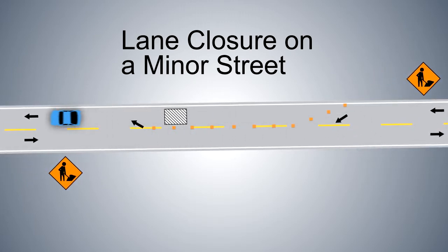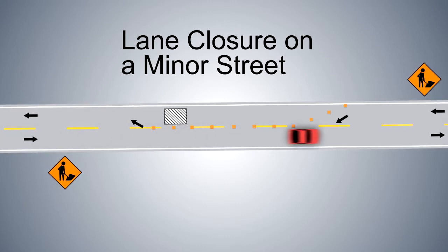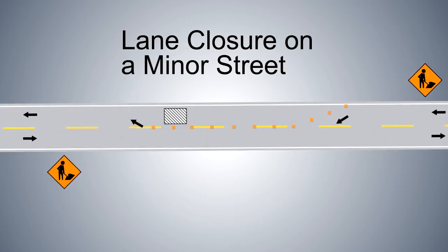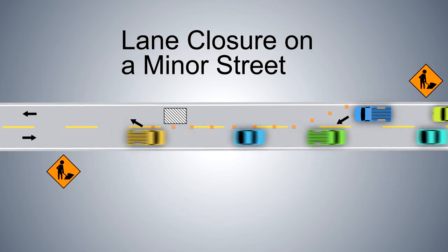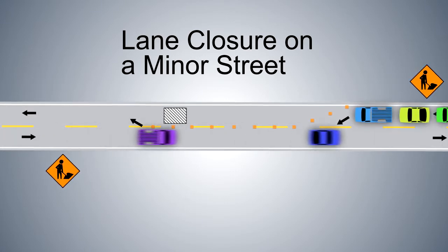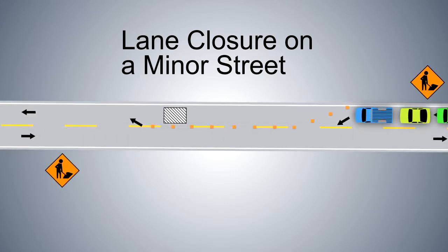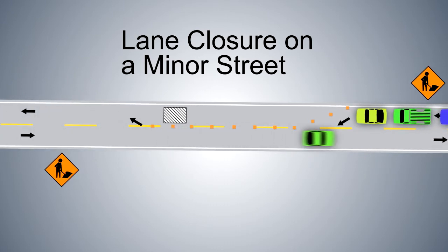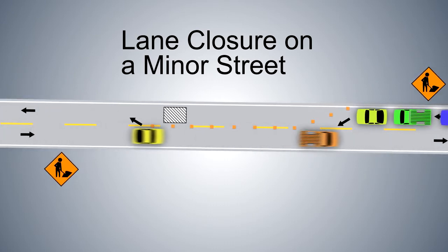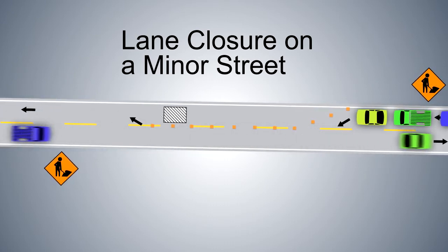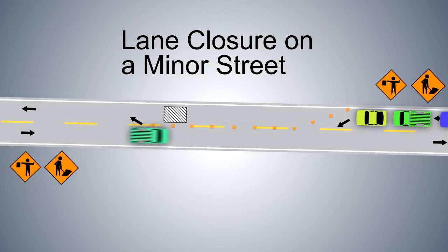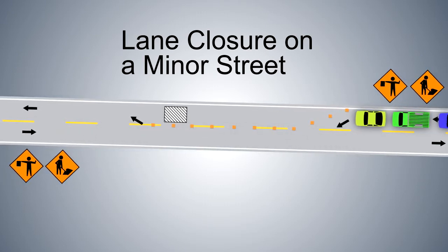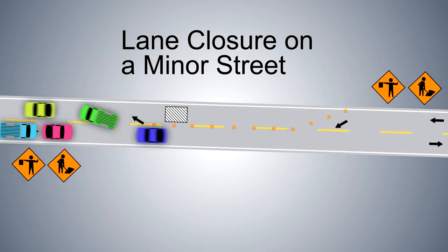However, when he arrives at the work zone, the supervisor sees heavy traffic in the eastbound lane and a backup in the westbound lane. To pass the work zone, many drivers accelerate too quickly. In situations like this, when traffic does not self-regulate, the standard in the MUTCD requires the addition of flaggers, which the supervisor immediately arranges to manage the right-of-way.